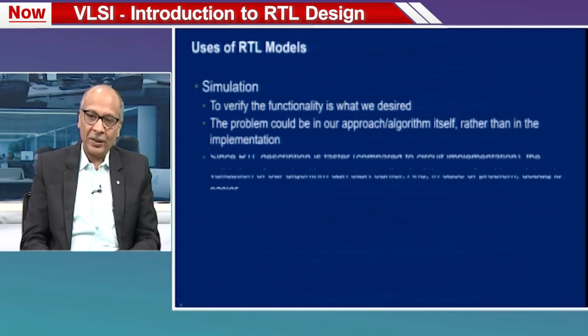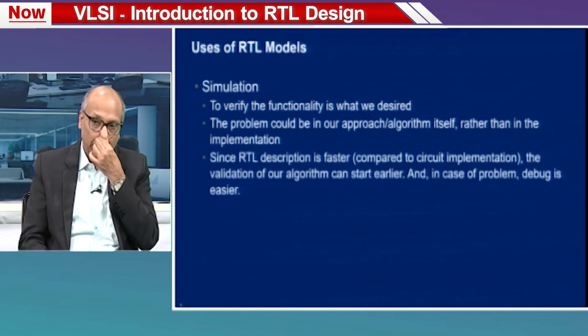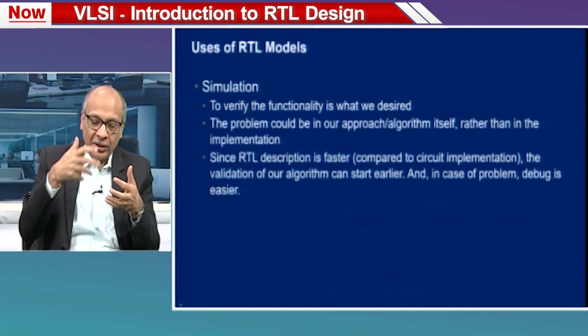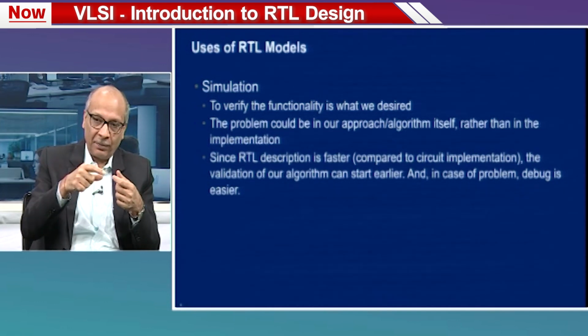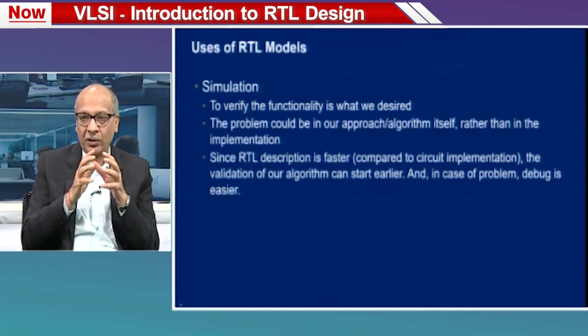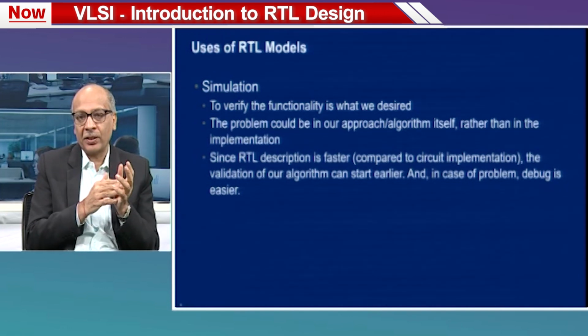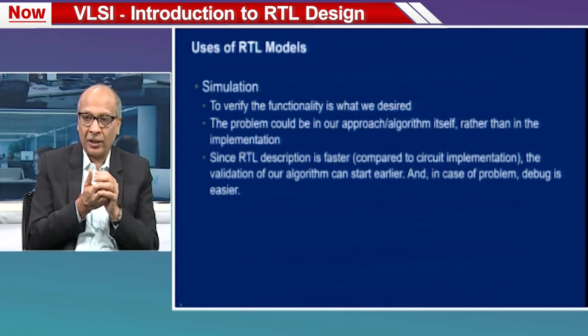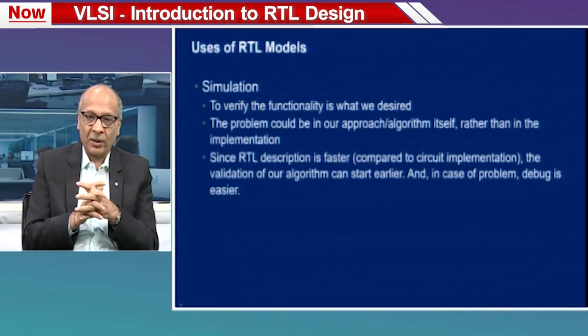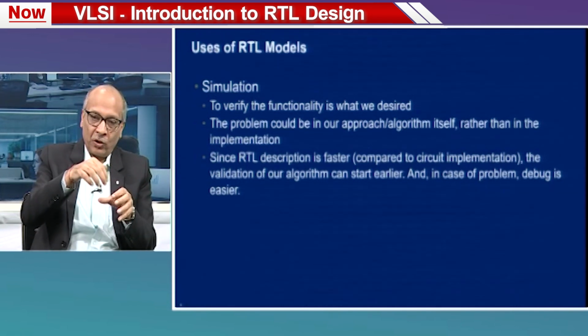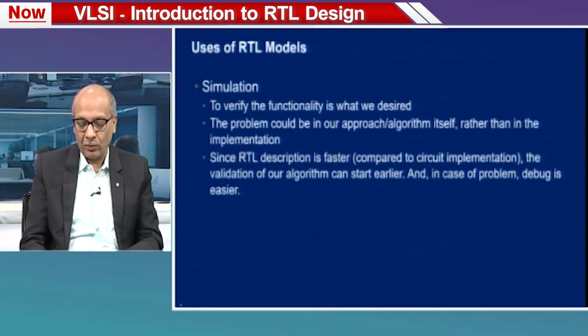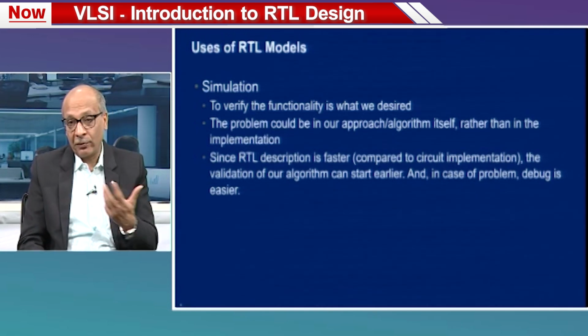So, simulation is one major usage, and since RTL description is, and we will see an example of how RTL description can be coded much faster, which means we can validate our circuits or our algorithms much earlier. Also, debug is easier because, like I said, the simulation allows us to probe signals inside a block and module, something that may not be very easy on hardware.